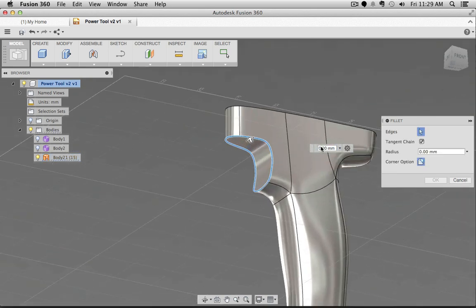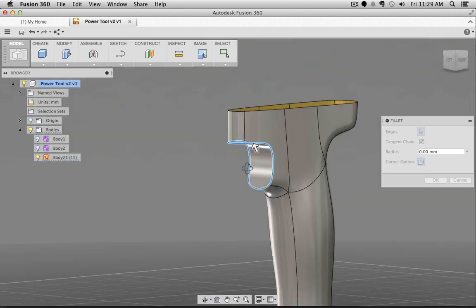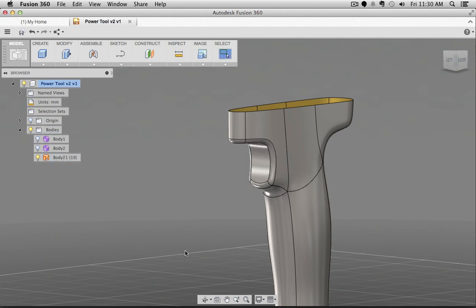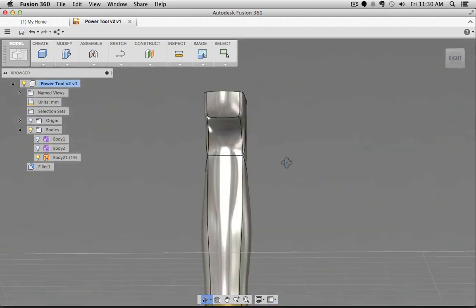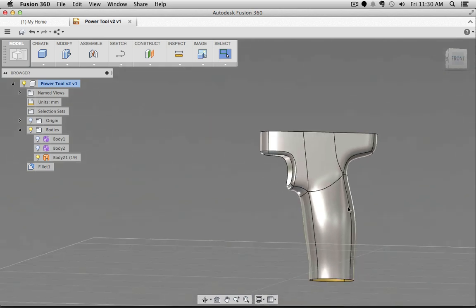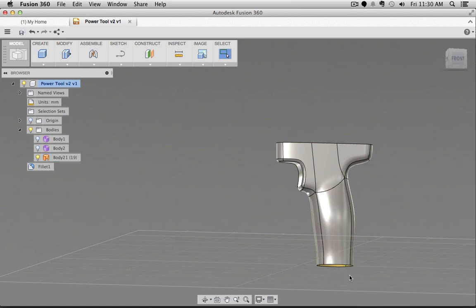And then you get a small new dialog. For example, there is a small arrow, and just check out what happens if I click on this arrow and slightly move it inwards. Small steps, 2.5 millimeters. You see it's actually rounding that edge and interactively creating those new surfaces for me. So that's why I said, for example, in your design process, think about styling proportion in everything, but wherever you have a sharp edge or we need to have a transition, for example, the transition of the battery handle into the battery pack, those are final details you do at the end.